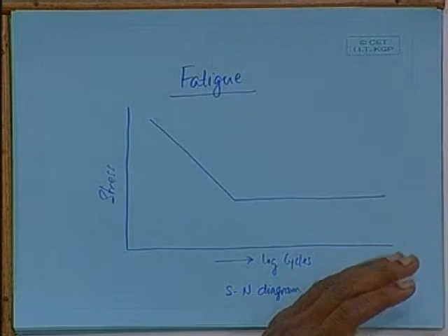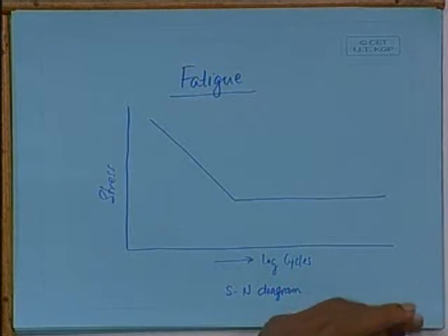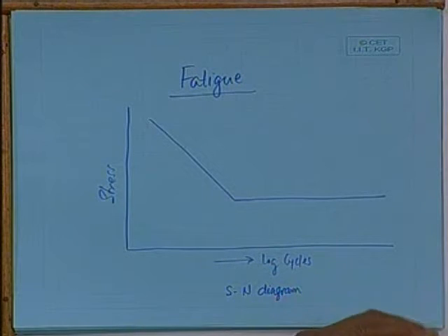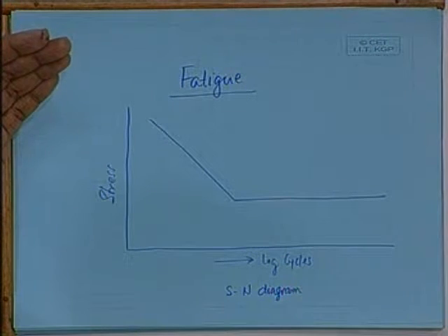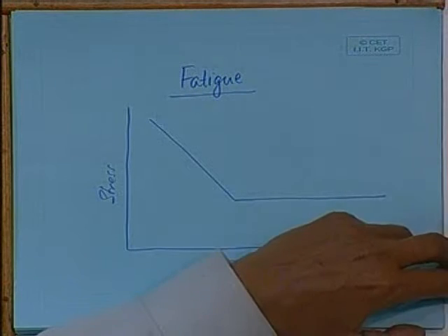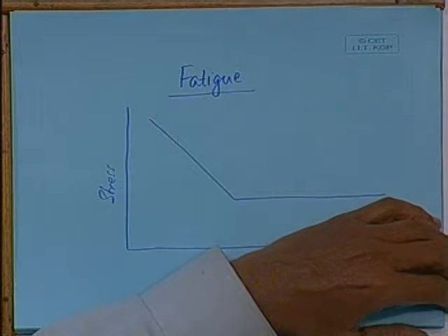When a metal is fatigued, it tends to strain, that is, it elongates. Once it elongates, this curve is no more valid and it is likely to fail. It goes beyond the elastic limit. It is actually related to the amount of strain the material is going through. So, when you use high tensile steel or high strength material, we normally go for more stress levels, more elongation, thinner material, therefore again more elongation, and therefore we compromise with fatigue strength.